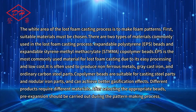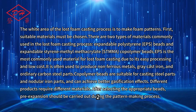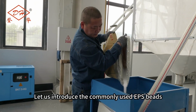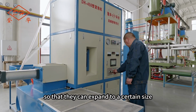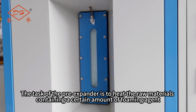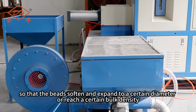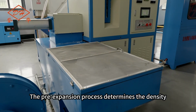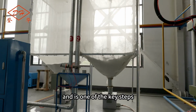After selecting the appropriate beads, pre-expansion should be carried out during the pattern making process. Second, pre-expansion. Let us introduce the commonly used EPS beads. EPS beads need to be pre-expanded before they are put into the mold so that they can expand to a certain size. The task of the pre-expander is to heat the raw materials containing a certain amount of foaming agent, so that the beads soften and expand to a certain diameter or reach a certain bulk density, while retaining a certain amount of foaming agent. The pre-expansion process determines the density, size stability, and accuracy of the model, and is one of the key steps.